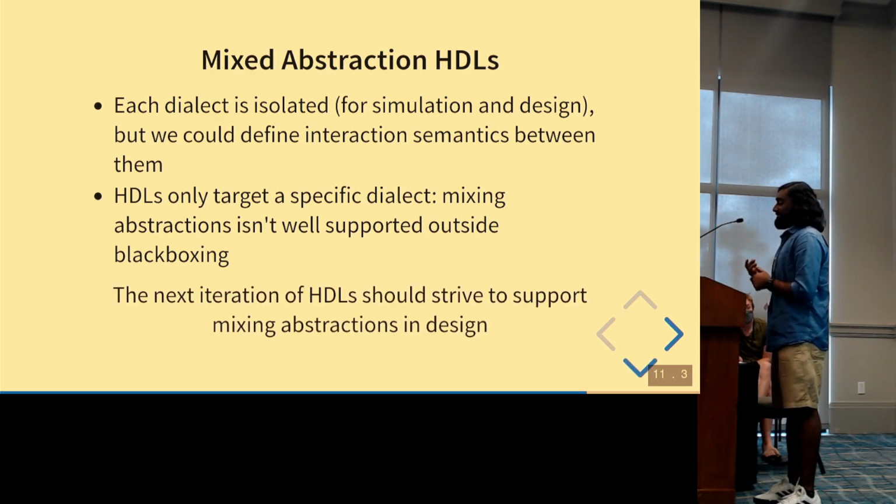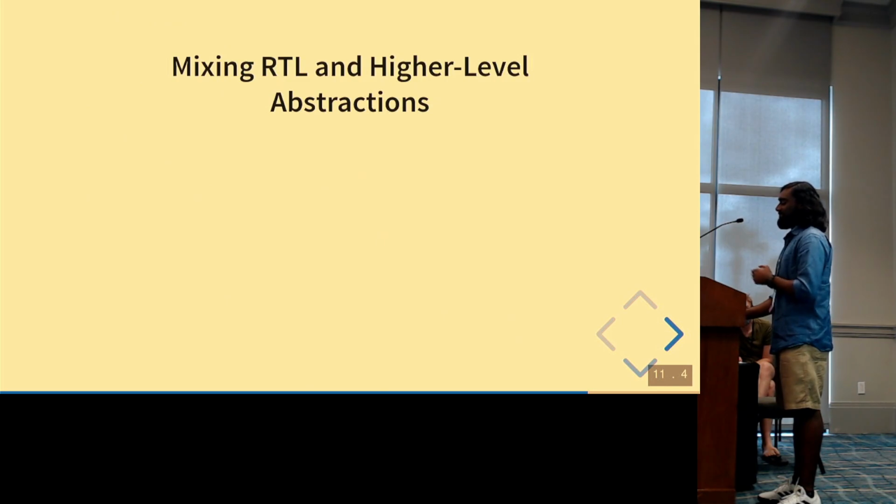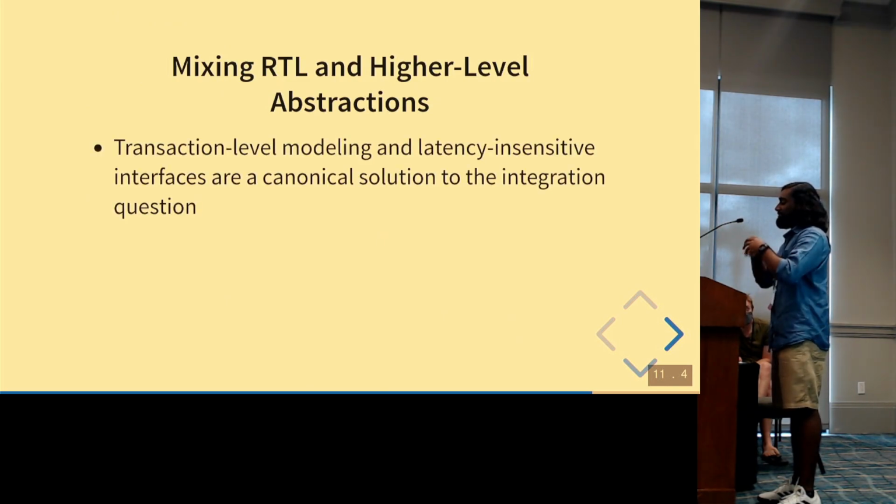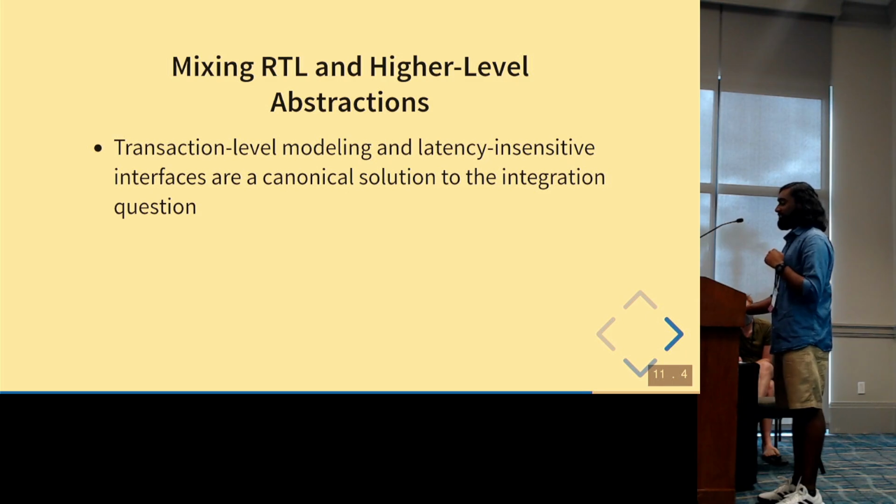I'd say that for this next iteration of HDLs, we should try to support mixing abstractions in the design language. So how does this potentially look? When trying to mix RTL and higher-level abstractions, transaction level modeling and latency insensitive interfaces are a canonical solution to the integration question of how these two things should talk to each other.